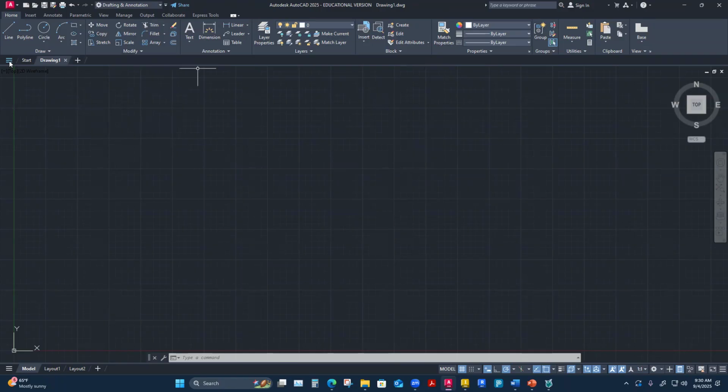I don't think I brought up these little three drop downs here. Another place to start a new drawing, new or open or save or close. So it's like a little quick access there too. I use this one probably the least. I feel like I save from the top quick access mostly, but you'll learn whatever way you like to flow through this. We talked about the command line. Anytime I'm in a command and I'm doing stuff, if I keep track of the prompt line down here, sometimes it helps me know what I'm doing. If I'm having issues with a command, pay attention to your command line. You might be trying to do something that it doesn't allow you to do. I like that it has a little text visual telling you what's going on when you're in a command.